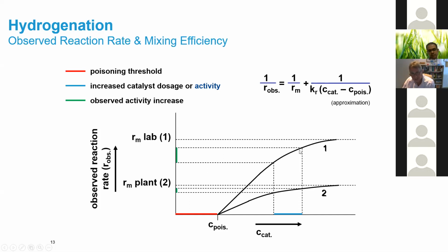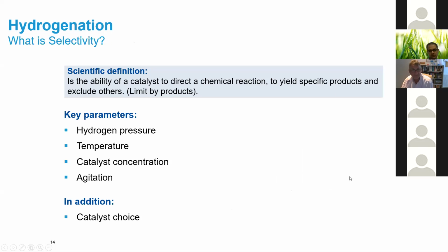You'll see that you get beautiful ideal conditions because you've got perfect mixing in the lab. When you get this out on the plant and you get less than ideal mixing, then that's the kind of reaction rate that you might see. I've cartooned the situation to show you that there can be quite a difference between lab, and usually is quite a difference between lab and plant reactions.